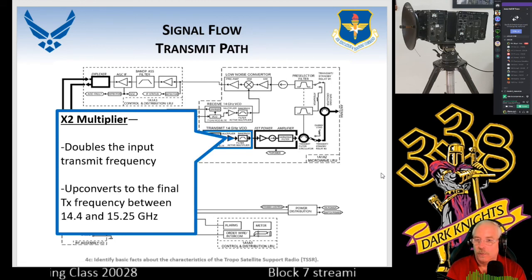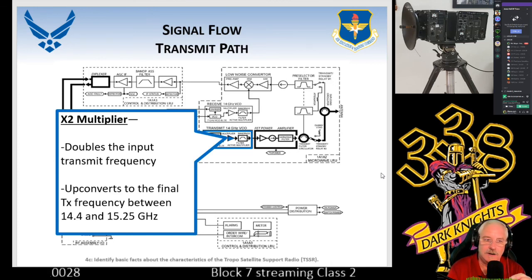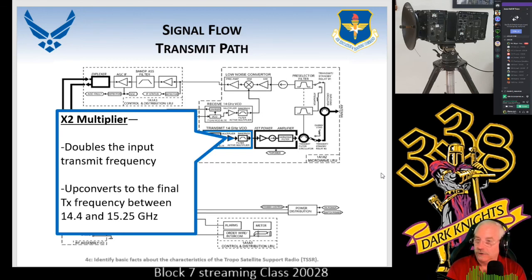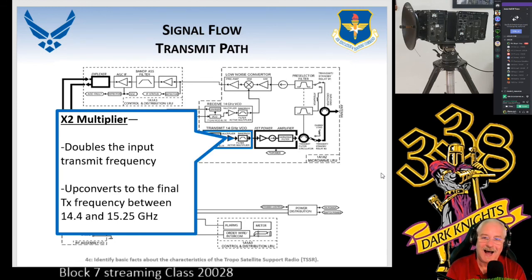That's the reason why when it appears that it's heterodyning, which is in some cases true, but we call it modulation because of that one little factor, because heterodyne, the definition would be when you take a nonlinear device and you combine 2 signals, you're going to get 4 out. Well, in this case with modulation, you only get 3 out because the impedance of the circuit wants the higher RF, not the lower RF, so it gets trashed. It's not able to get through.